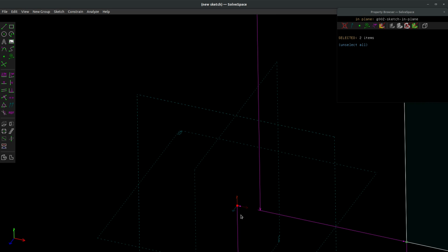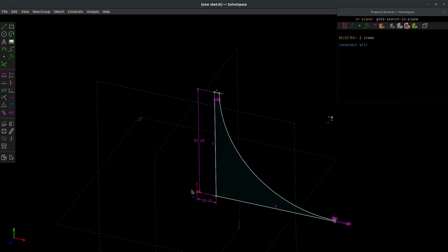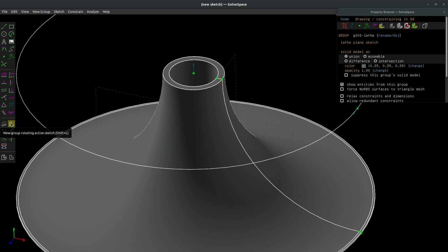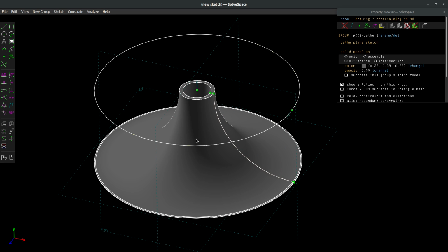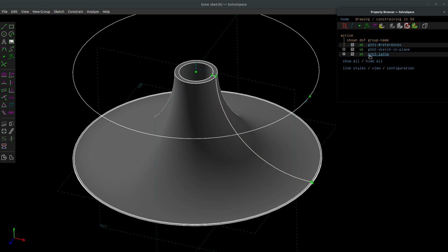So in this case, the axis is placed on the origin, and in the vertical, you'd say this green axis is orientation here. With those two selected, I can now revolve, and I simply click on this button, and we're given a revolve of our sketch. Really handy, pretty simple. Let me break that down a little bit more, though, if you have any further questions.